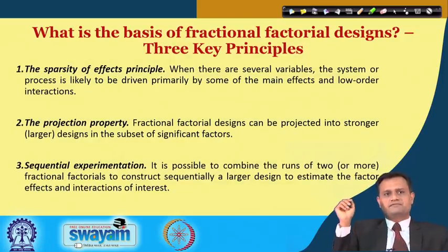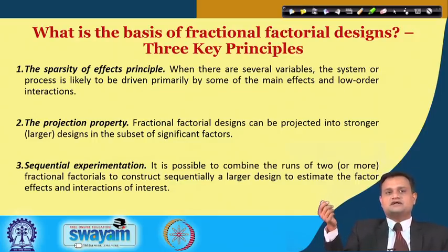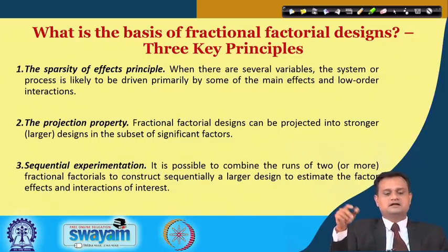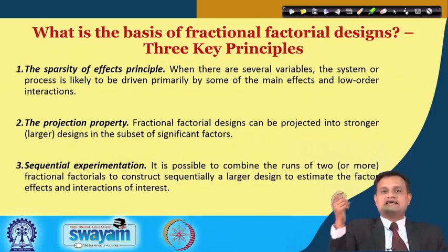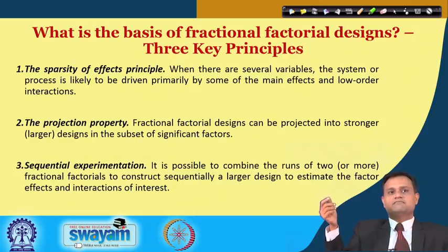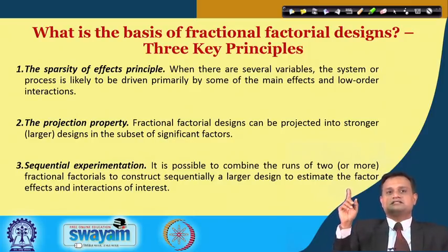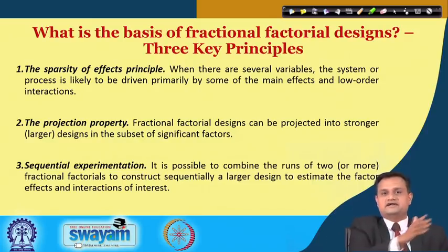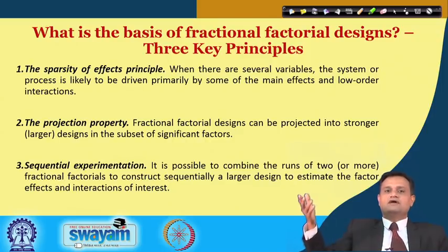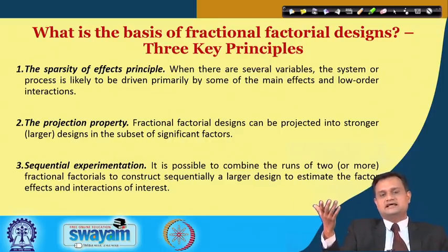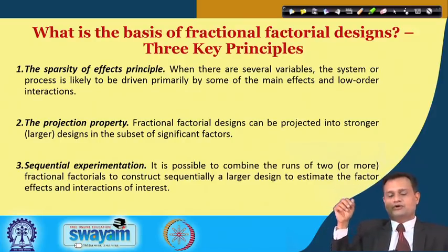So there are three important principles to be appreciated, and they create the basis for fractional factorial design. Number one, the sparsity of effects principle. When there are several variables, the system or product is likely to be driven primarily by some of the main effects and low order interactions. Many higher order interactions, maybe 3 level, 4 level, you may say that they are not very much impacting my response, and this is principle number one.